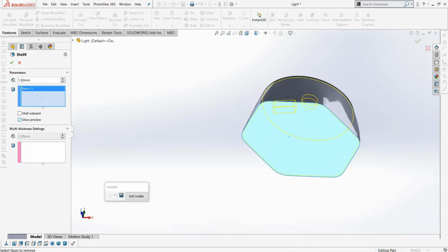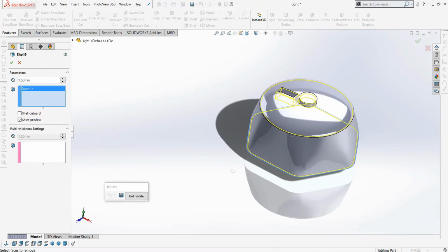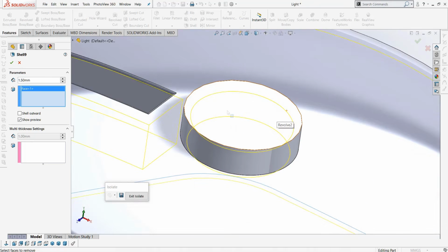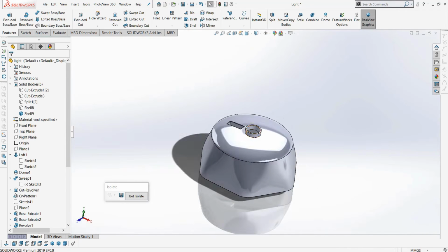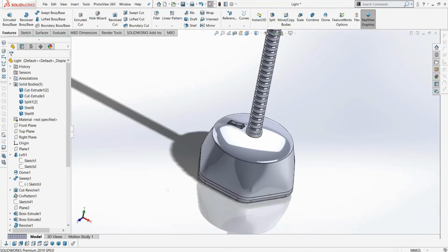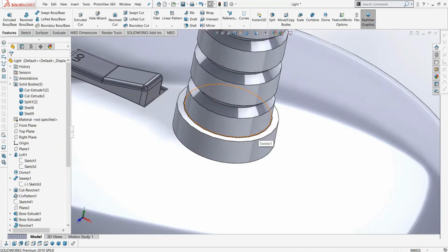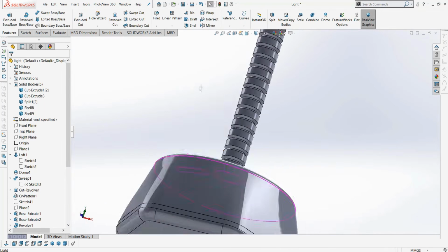Well, let's make a 1.5 here. As well, just leave that bottom surface and select this top one too, so that it is solid. Now, these two should be removed, and in the meantime, make it hollow to a thickness of 1.5, which is excellent. Now, why did I do this?